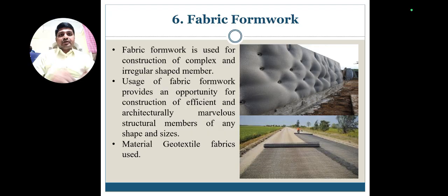So that is the main advantage of the fabric formwork. It gives different and undulating structures for the construction field. Irregular shaped members become possible, and usage of the fabric formwork provides an opportunity for the construction of efficient and architecturally marvelous structural members of any shape or any size. Here the material used is geotextile fabric.